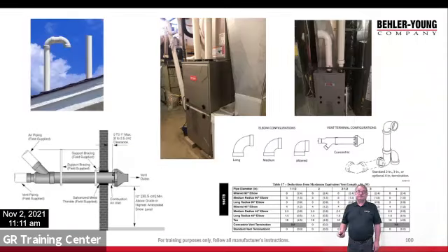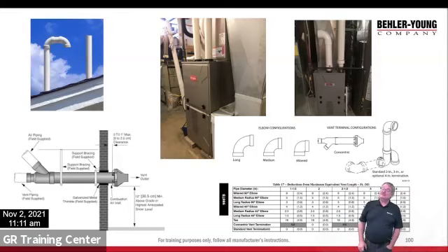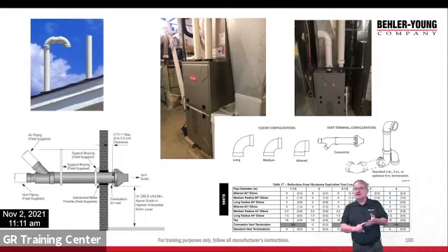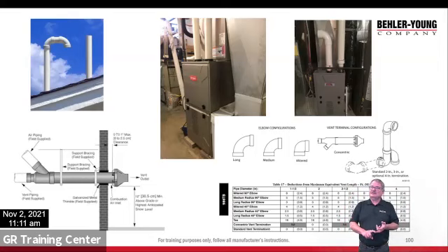Okay, so a modern 90% furnace. Venting is very specific. So whatever brand furnace you're dealing with, you've got to get the chart they provide. It's going to tell you what size pipe, depending on how long it is and what size the furnace is. Okay.